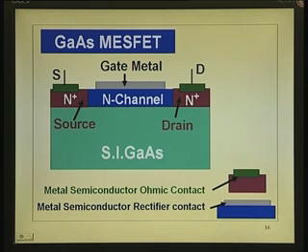You can see here, this tells what actually it is, the gallium arsenide FET or GaAs. In this example that I have shown, the semi-insulating gallium arsenide. I have shown this layer, full layer, which could be implanted layer or epi layer etched otherwise. So, you have got here source which is N plus, drain which is N plus, and then metal contact here.